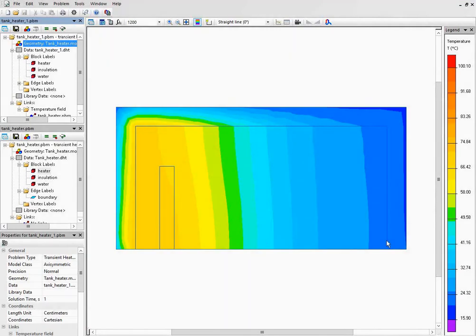So far, we ourselves acted as a control system, manually switching on and off the heater. Now let's build the automatic control system. Before building the control system, let's adjust the problem setup. To limit number of problems in chain, we will build the closed loop of just 2 problems. To make a loop, we should put the reference from the first problem to the second one.